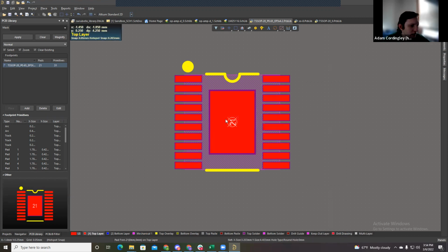I usually leave it up to the designer who does the PCB to do the thermal vias. I don't usually do those in the footprint, even when the data sheet recommends it. I always leave it to the designers because it gives you more flexibility with your drill sizes and the precise placements in case something were in the way. It's just better that way. Everyone knows to add thermal vias to their exposed pads when needed. So I don't find it necessary or a good idea to add them to the footprint itself.